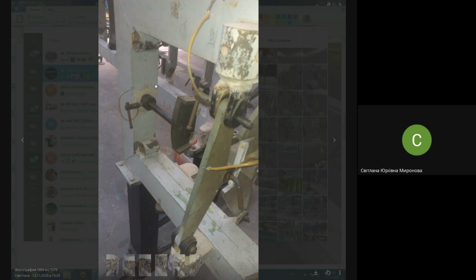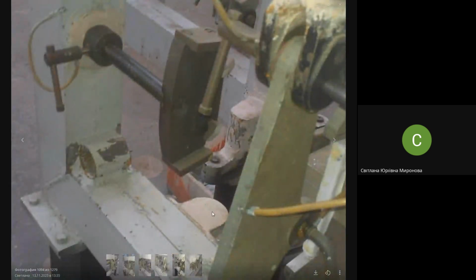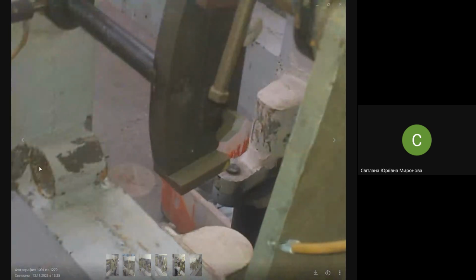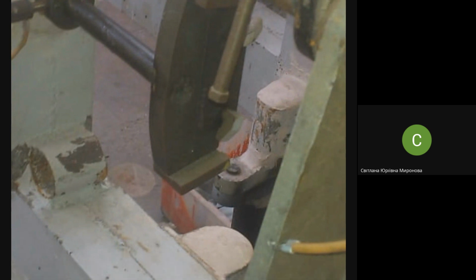What is the idea and main advantage of such a design? It is another way to join elements of the jig to the skeleton, to the carcass of the jig, or to each other. Here you see an empty barrel without anything at all, without another element. Just stuff it with this cement. Yeah? And here is an empty barrel which is not in use. You see it's just a piece of pipe, which is roughly welded to the skeleton of the jig.